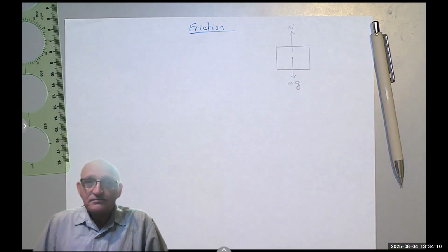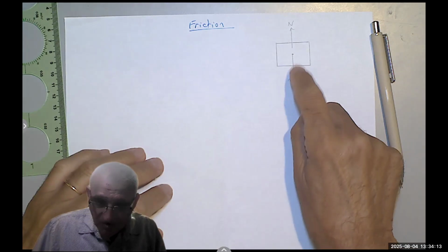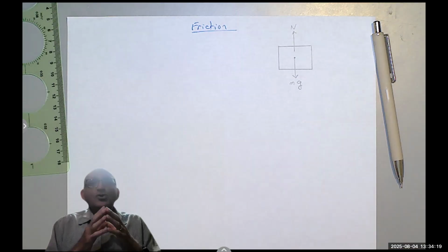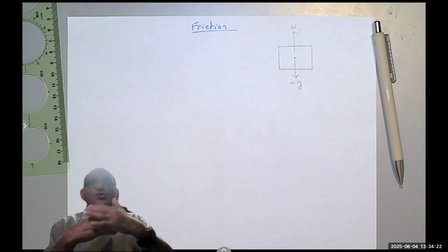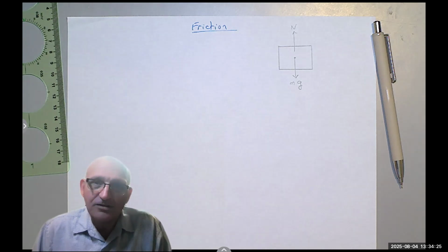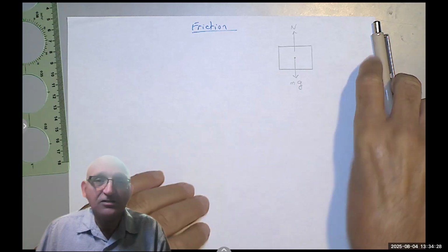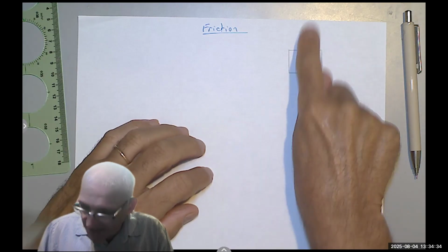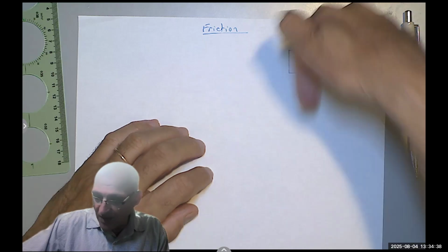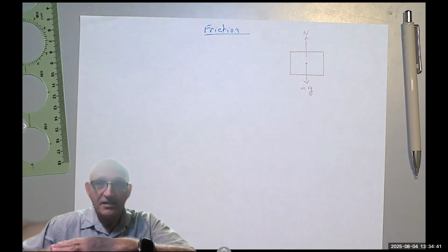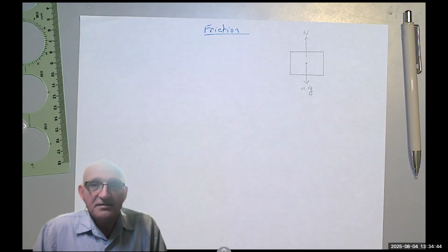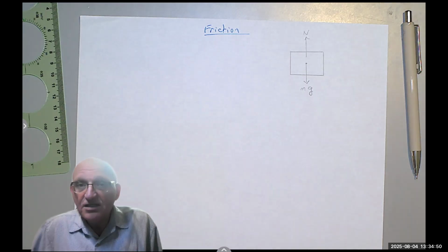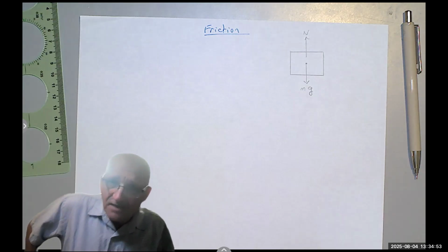And by the way, in fact, N is down here. I drew it up, I slid it up so you can see both. But the normal force always occurs between two surfaces because it's an internal force. And how many times so far have we said that internal forces always come in pairs. One of them is acting on this box or the crate, and the other one is acting on the surface that is holding the crate. Okay? So we have two equal, opposite, collinear forces. That's a particle. W equals mg. I'm done.